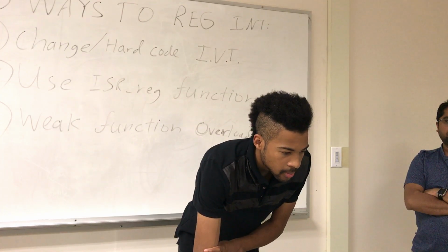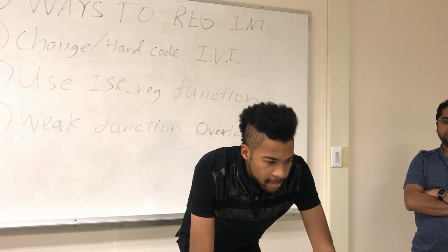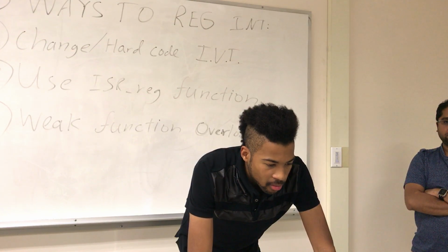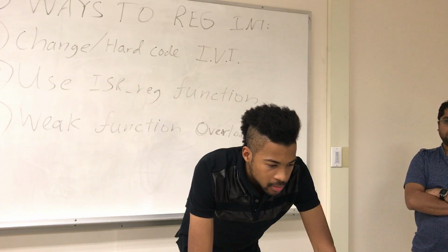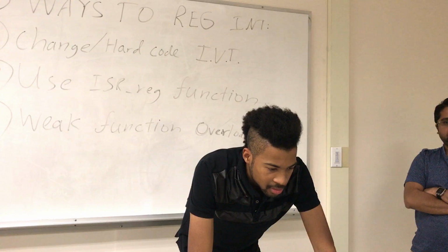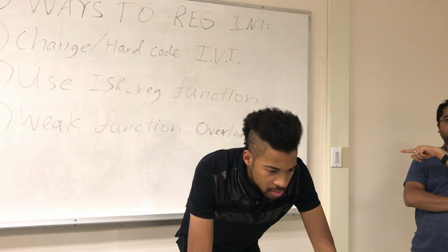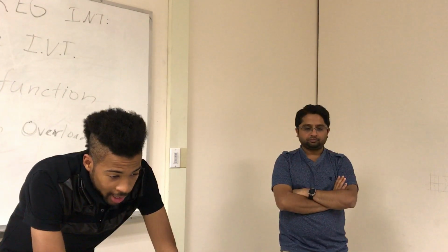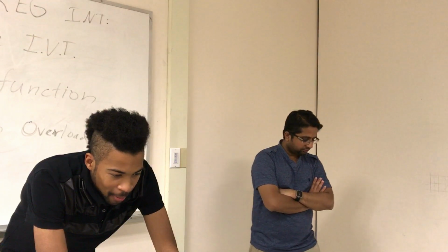Yeah, go step by step. That's the only way you will be able to solve this problem. So choose a pin, choose what kind of interrupt you want to act upon, a rising edge or a falling edge, and then write a small routine that gets triggered. If you can follow that for one pin, then you can extend that for other pins. Absolutely. Get the minimum viable product done first, and then move on.